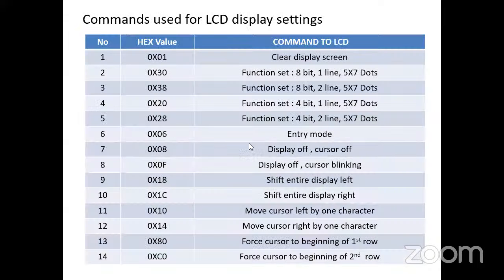Next, entry mode. 08 is used for display off, cursor off. 0F is used for display on, cursor blink. Display off, cursor will blink.